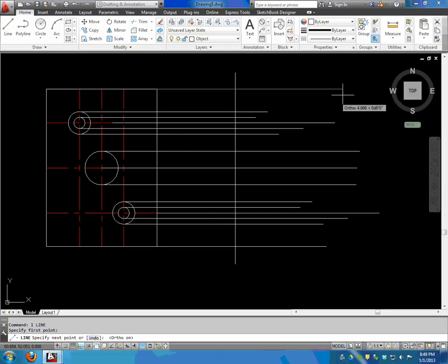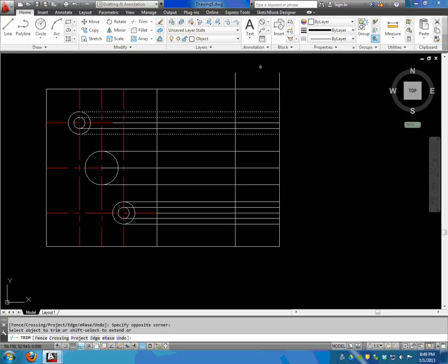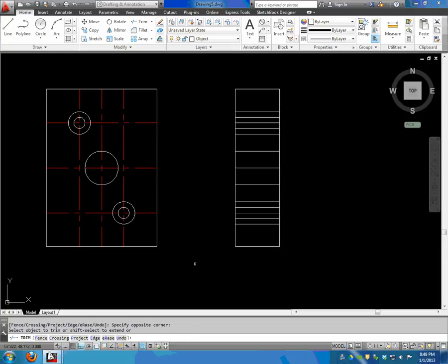Ortho back on. So we know that part's 1, so we'll do an offset. As you're watching these videos, if you prefer to see the keys punched, please let me know. 1. I get in a habit trying to get these done. Extend. So right there. Now I'm going to do a trim. Actually, we need to put the counter bore in first. Now we could do the trim first. Clean this monstrosity up here. Okay, offset. Offset and do depth of 0.8, 1 divided by 8. Then you can offset that way. So we have that counter bore done.